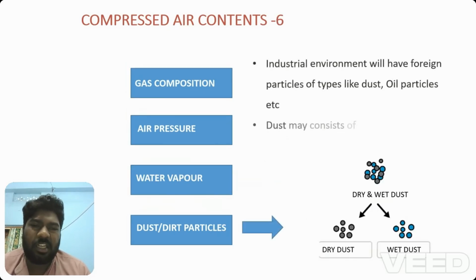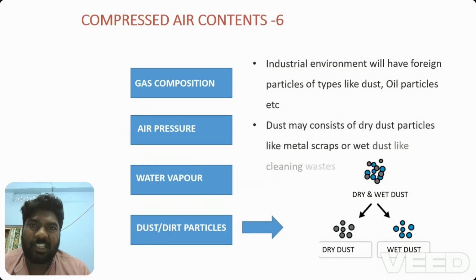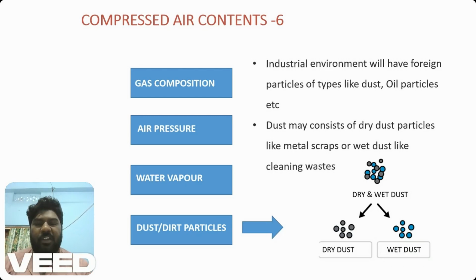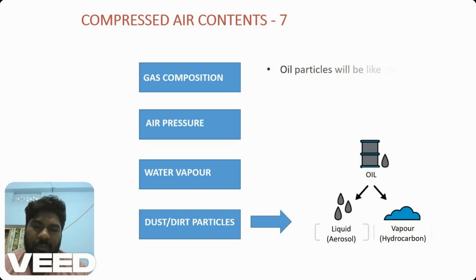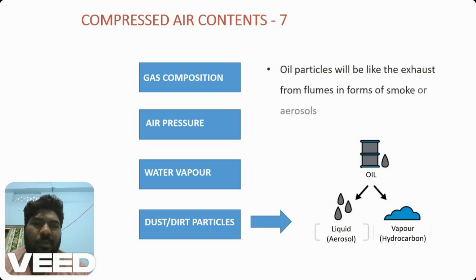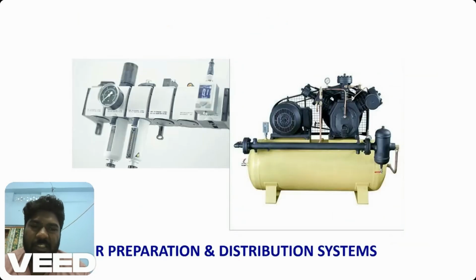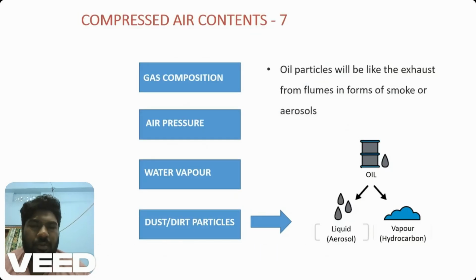These dirt and dust particles are further classified into two types: wet dust and dry dust. Dry dust is not a problem, but there might be problems with wet dust. Wet dust is nothing but whatever the oil we have been using, that gets vaporized and mixed up with air, and that will be creating a problem. So to remove these, we'll be using aerosol filters, all those.